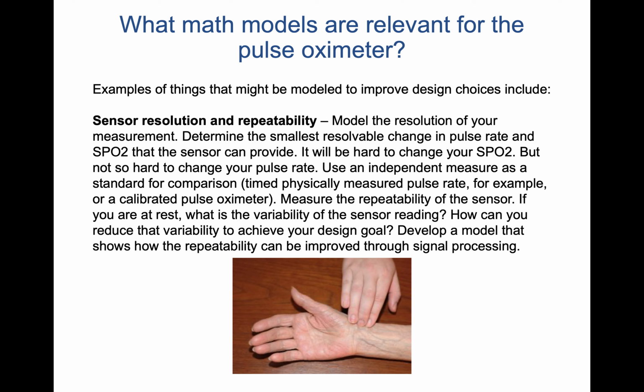Measure the repeatability of your sensor in comparison to this standard. If you're at rest, what's the variability of the sensor reading? How can you reduce that variability to achieve your design goal? Develop a model that shows how the repeatability can be improved through some kind of signal processing, typically averaging.